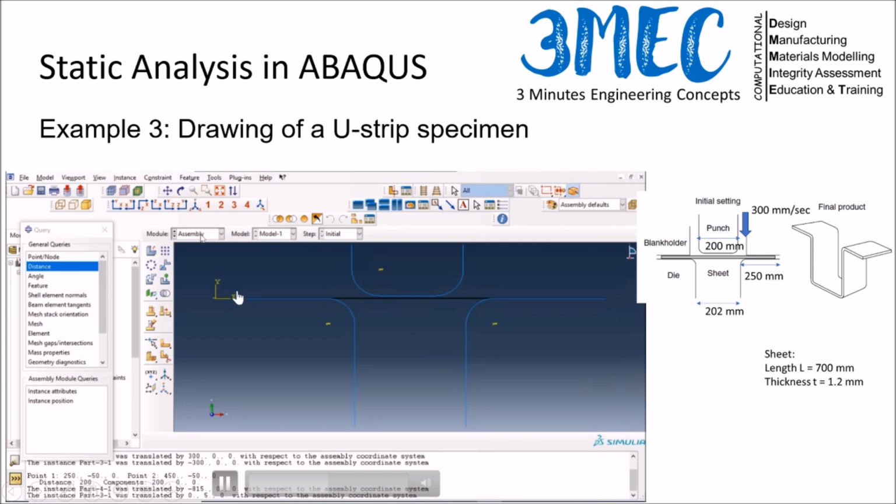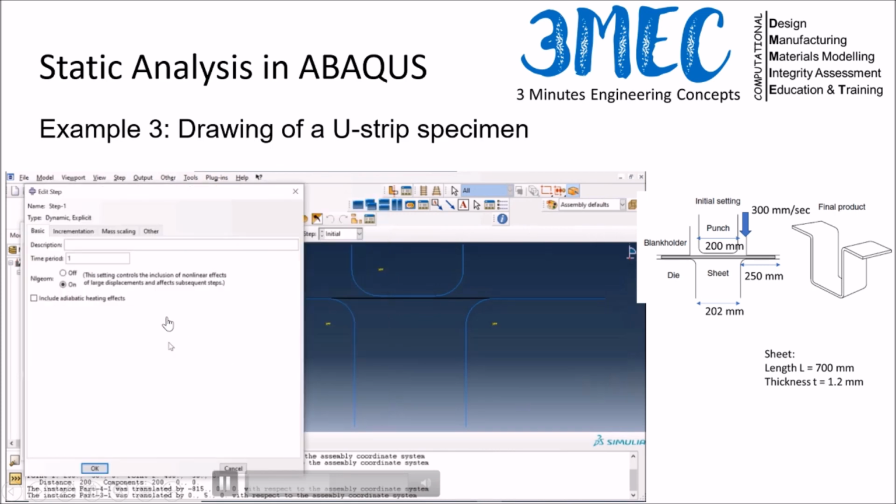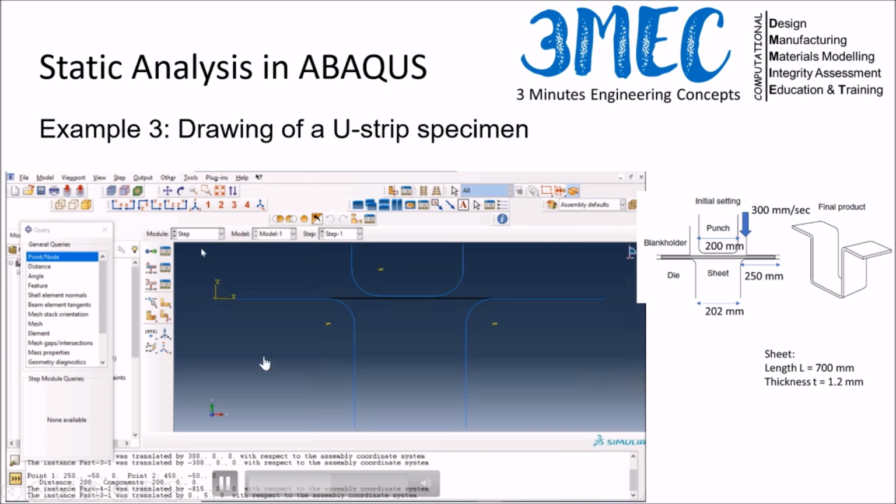Okay, now what I do is I go to the step module and I create an explicit dynamic step, which is somewhere on the top here. Yeah, and then I run it for 1, and everything is default, and I just press OK. So now all the default values have been used in this case. Next step is to define the interaction.